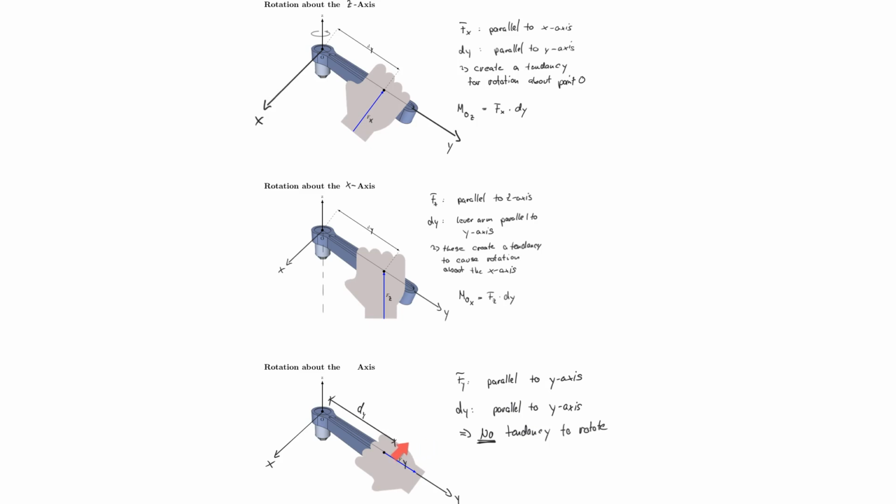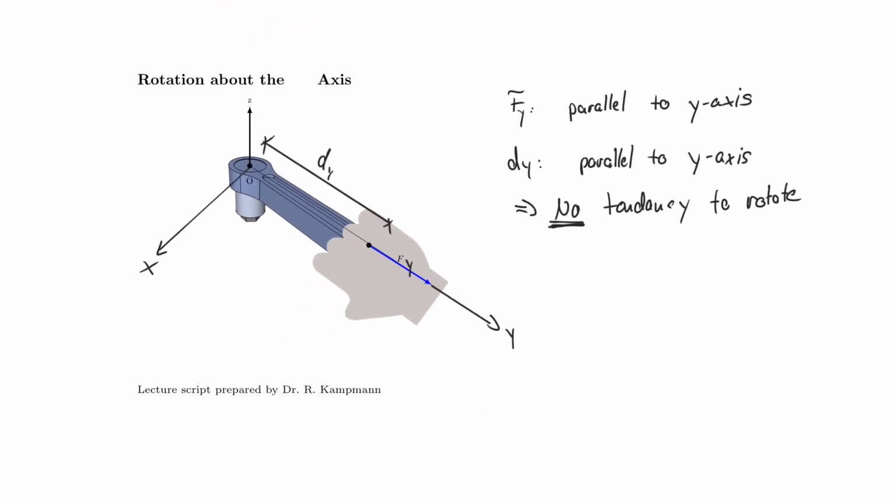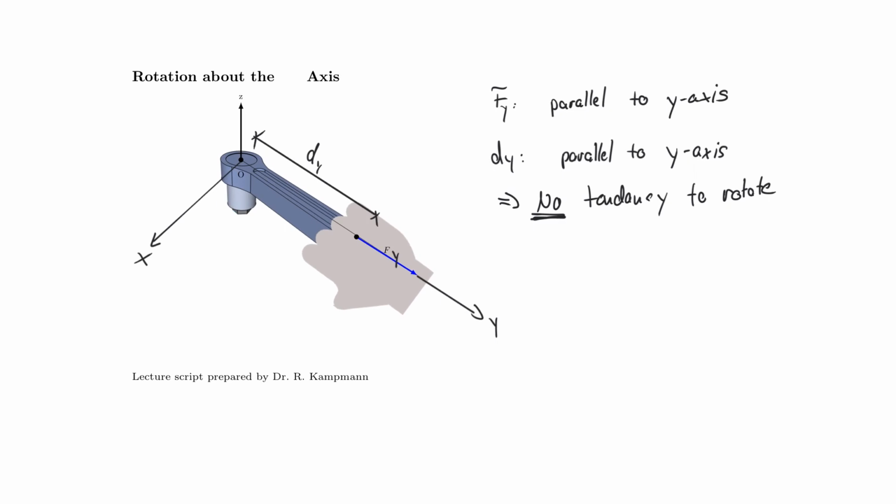But physically speaking, it's actually more important to think of this as the point of interest. So the problem here is actually that the force passes through the point of interest. So Fy is passing through this point. The line of action of Fy passes through the point of interest. Let's write that down. That is very important.